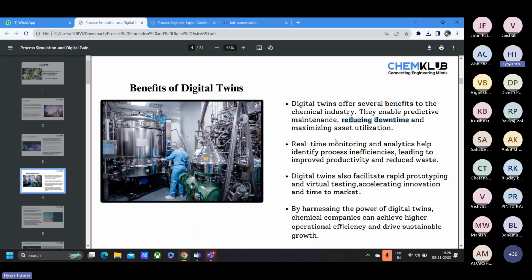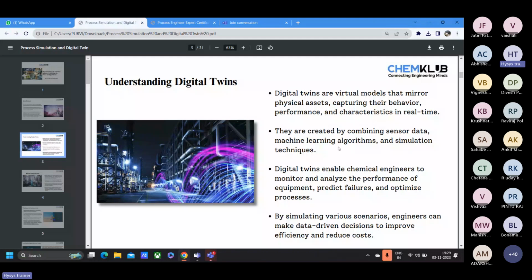Now, what digital twins are doing is taking that same particular model of simulation. For example, for the compressor, the input conditions provided in the digital twin are the temperature, pressure, and composition of your streams. All that information they take directly from the plant with the help of your instruments, that is pressure transmitters, temperature transmitters, or the analyzers of your plant, and then they feed it directly to the model of your compressor, and then they run it.